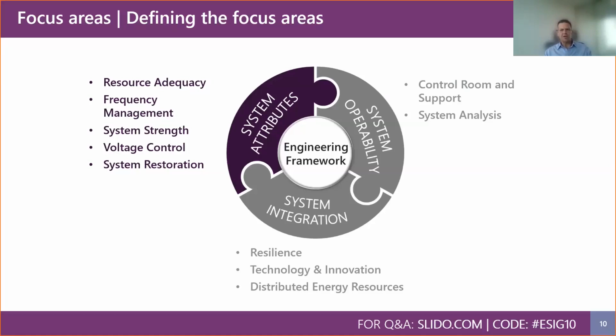Voltage management is similarly a large catchment that includes both static and dynamic voltage control. It also goes beyond the simple management of voltage at the transmission level, and it needs to explore more deeply planning at the transmission and distribution interface, particularly given that we're seeing so much growth in DER, as well as the continuing and increasing decentralization of the generation fleet. System strength is also going to continue to challenge us, particularly as this decreases and creates more complex scenarios to operate wind and solar generation in.